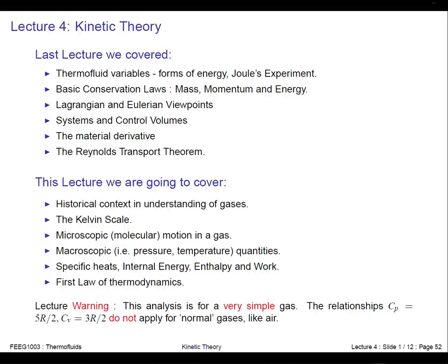So we made a few definitions about systems and environments and control volumes, and then we ended up working out the material derivative and the Reynolds transport theorem, and these are the tools that allow us to change this frame of reference. Okay, so we did it using conservation of mass, but we can do it, and we'll do it later on in our module, for conservation of momentum, conservation of energy.